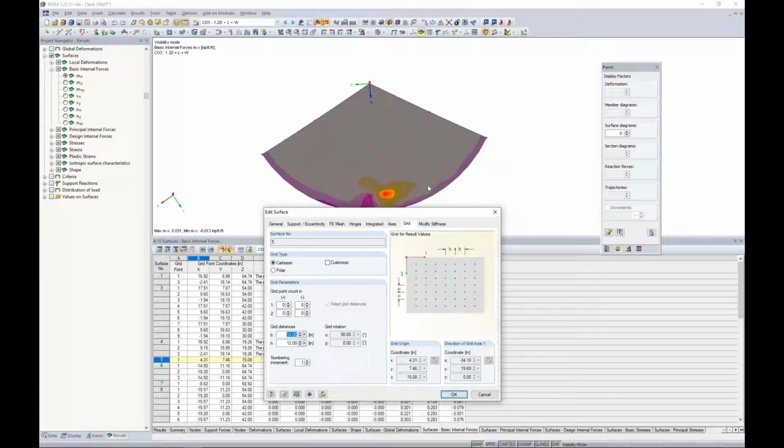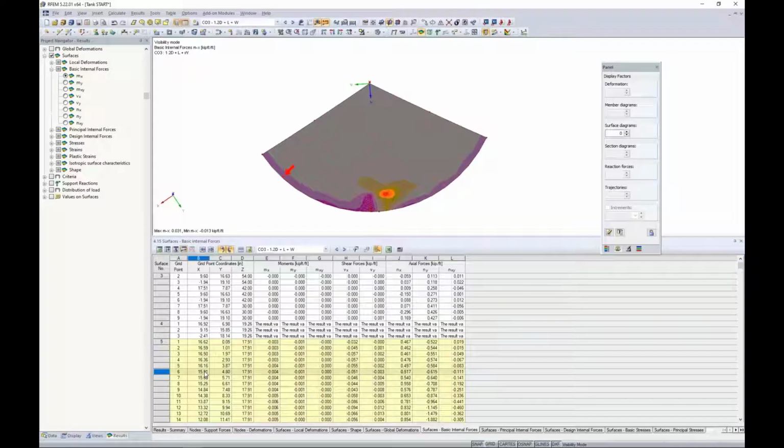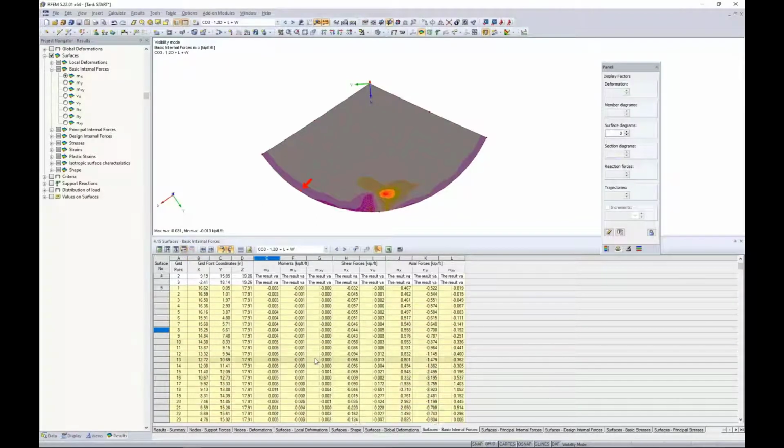Now, this tank structure is fairly small, so we need to go back, and in Webinar 1, we did this with the FE elements. We want to do the same with these grid spacings to change this to maybe something like 0.5 inch spacing. And I click OK. So now you'll notice with surface number 5, I have many, many more points available to me here. So this is obviously going to be much more beneficial than just a single point element.